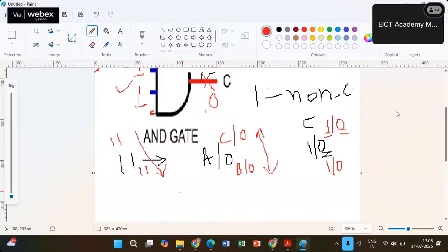Fault equivalence, by definition, what is the fault equivalence? If I have equivalence based collapsing, we will be doing: if the faults are equivalent, we will remove all, but we will keep one. So we have taken the example of AND gate. If I have the faults stuck at 0 at A, B, C, any of the branch, in every case I need 1, 1 as the input, right? And since it is stuck at 0, of course I want stuck at 1. I want 1 as the true output. So output will be 1 0.